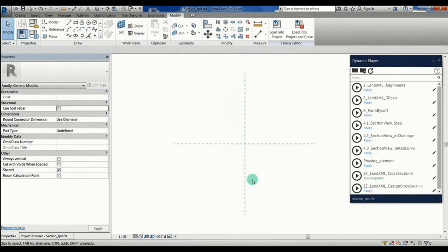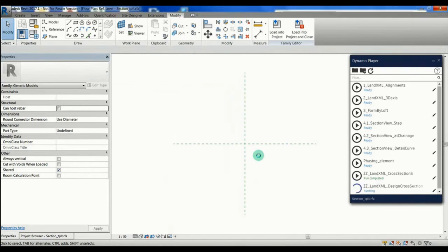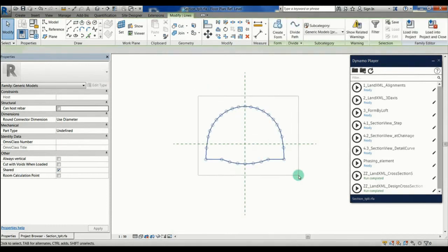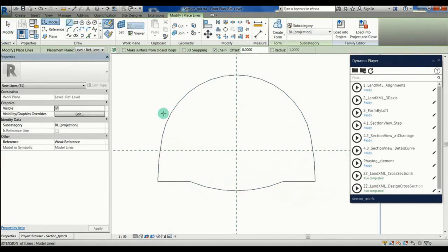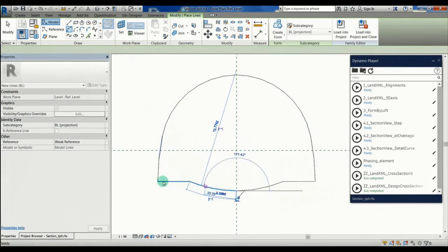I choose the first one, sorry. And then I run another script to create the points and the lines in Revit. So I will get the shapes and lines created by the model. It's in Civil 3D. When you create the section, I will get back everything. It's not a curve, it's just short lines and points. But I can use it to create my own stuff in Revit. Okay. So that's exactly what I'm going to do. So I will have my own section, and this section will help me to create my Revit model.